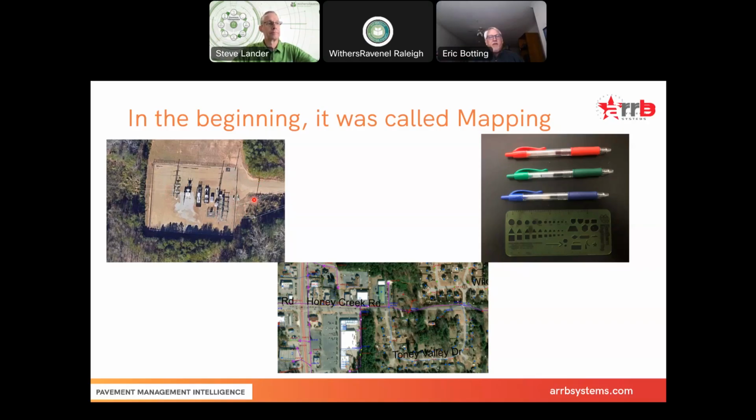Take it back to the office from the field, put it under the Mylar sheets that we had done of the background, and we would draft onto the sheets. We would create blue lines and deliver the blue lines. We would also have reduced blue lines for people to keep in the back of their truck so that anytime they made a modification of the system, they would simply redline the blue lines, and then once a year they'd send them in and they would get updated.